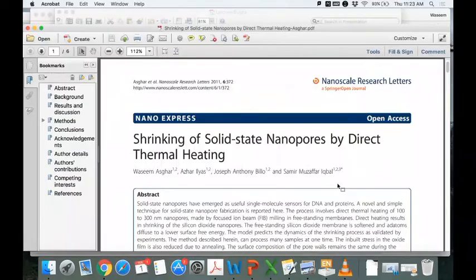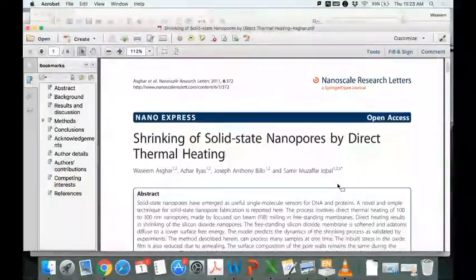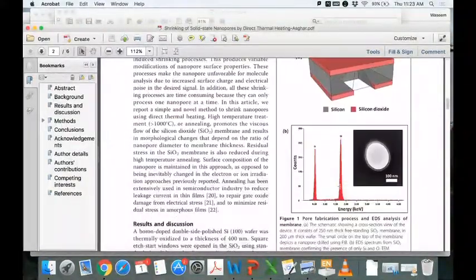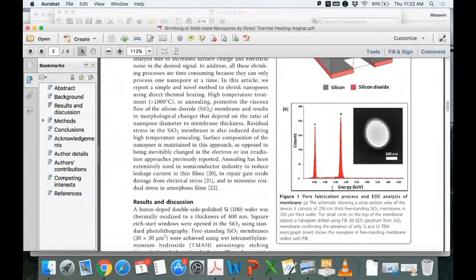So for example, this pattern: if you look at the energy which is being released and count these also, and then see how much we are getting. A very specific energy gives us this peak, and another specific energy gives us that peak. And that peak is linked with the silicon or oxygen, depending on the location. So let's say I have this material and I use EDS, this is another method to characterize.